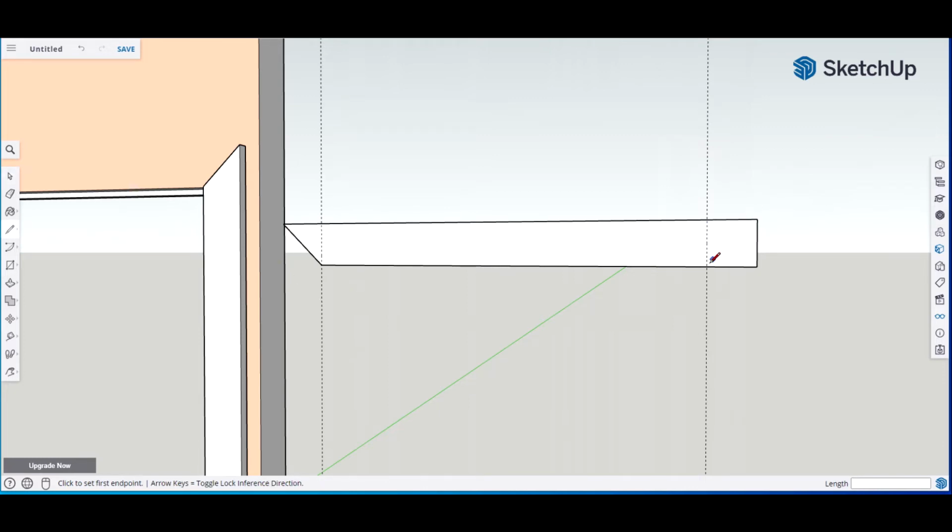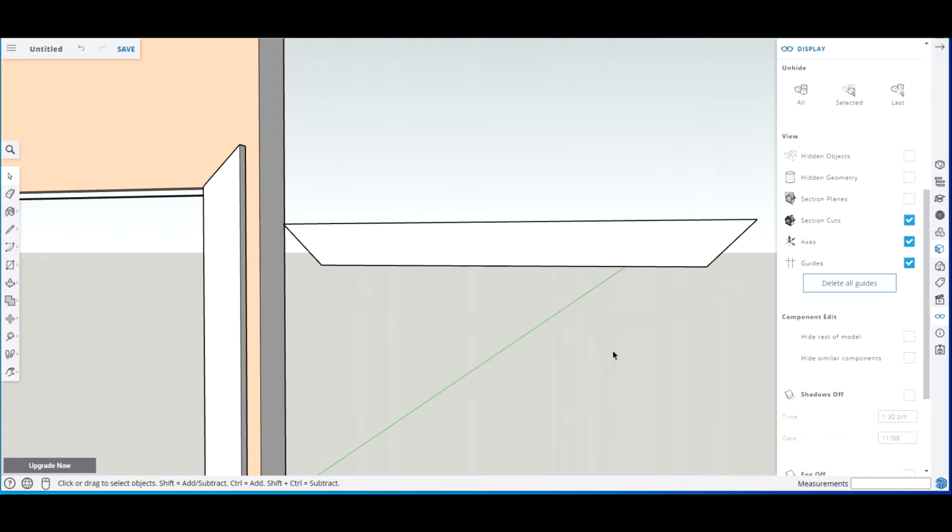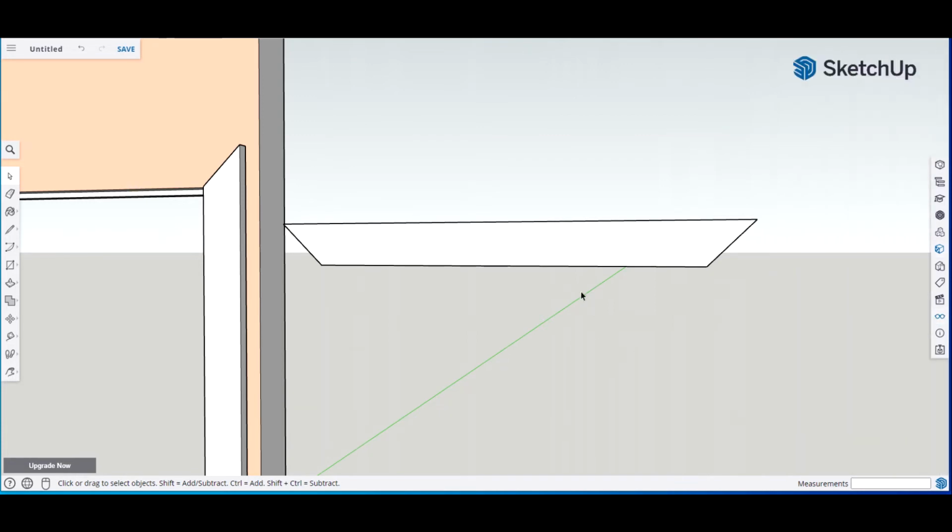Line tool, select L, do the same thing on this side. Space bar, highlight. Actually, you can hit Control, highlight, and highlight again, or you can hit E for the erase tool, but let's just do it that way. Delete, and now it's gone. Let's hit our glasses, delete the guideline, space, remove.